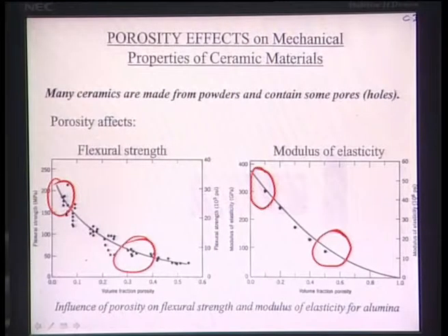But remember, when the material is highly porous, it also has consequently very low flexural strength. So, it cannot be used for highly load bearing implant applications, or in other words, in biomedical applications which require large load bearing capability.